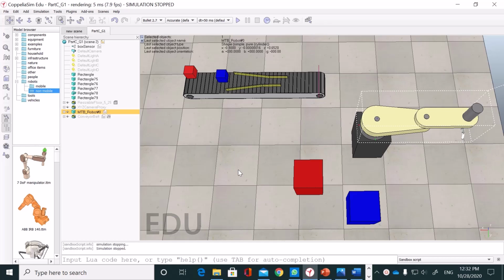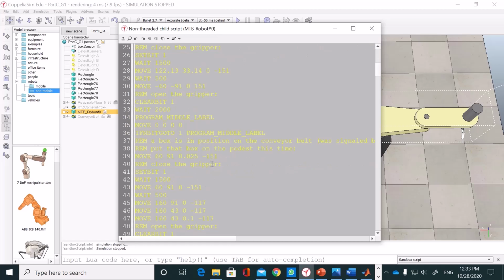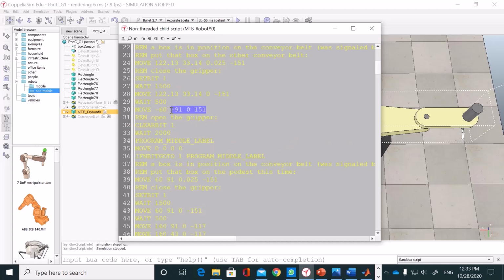We have seen that the robot grips the object correctly, and now why not you try to find out the location of the drop of the box, or the place location, which should be on the blue large rectangle or object, and you can use the inverse kinematics formulas that were shown and follow the steps, and later try to change the program by adjusting the values of joint 1 and joint 2 in the program file, at line number 30.